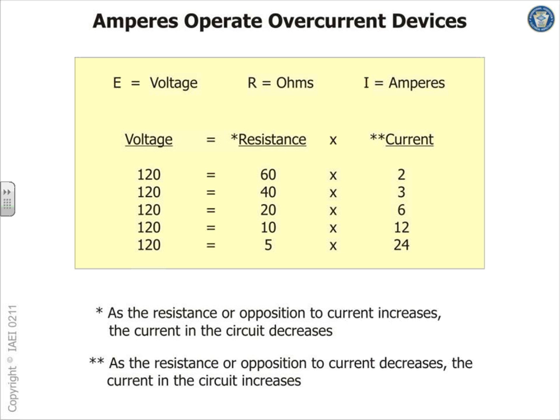Who cares? If you have a ground fault in any system, the main reason why we ground and bond the system is for safety. When you guys deal with 70E, there are two hazards involved from the science of electricity: the touch hazard, electrocution, and the arc flash hazard. That's really the two hazards. So when you ground and bond the system, you minimize both hazards.